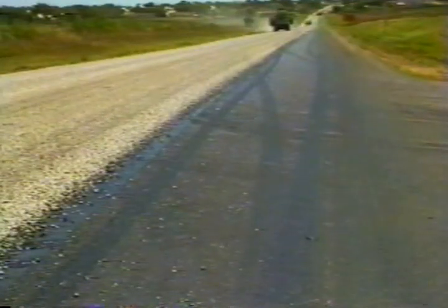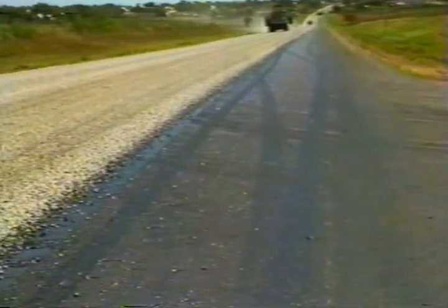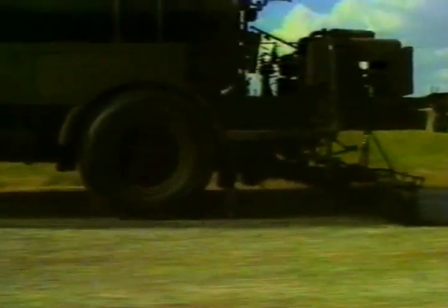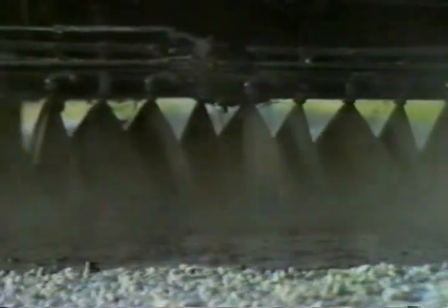The higher pressure also makes the oil spatter excessively, propelling droplets over the entire width of the adjacent lane, where tires of oncoming traffic will pick it up. But the most serious consequence of this problem is when the oil spatters onto a freshly chipped lane where it lies free to be picked up and tracked by tires. Another cause of surface oil is grass and debris that stick to binder-coated distributor parts and then drop into the spray path to be covered by oil.